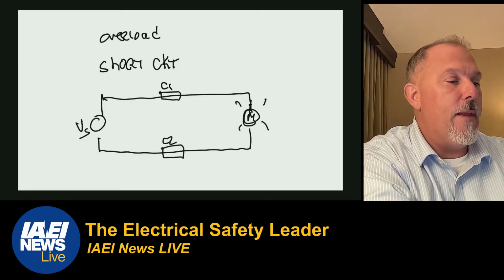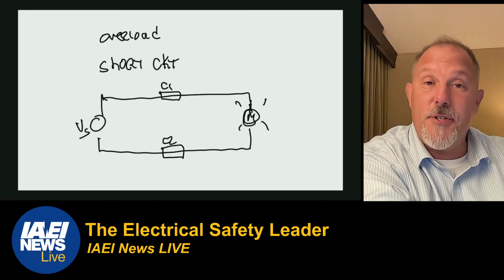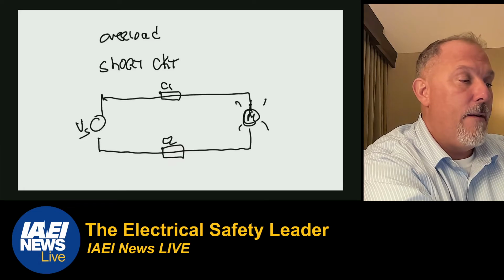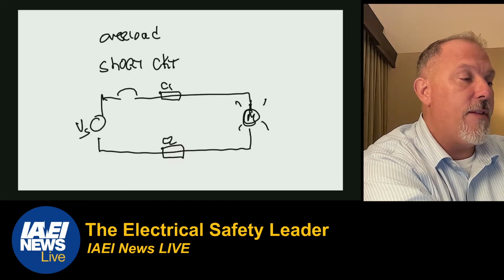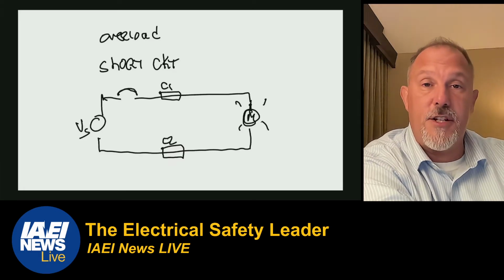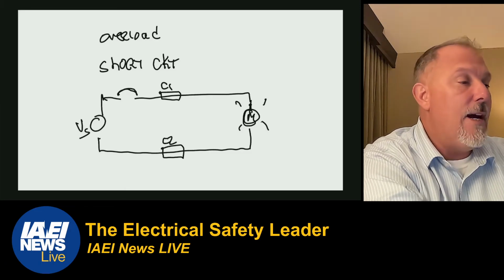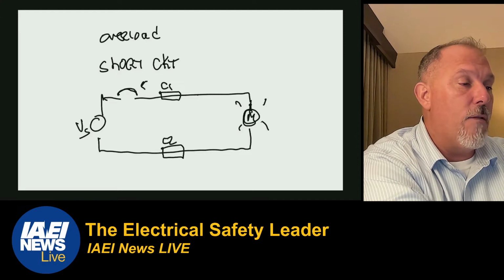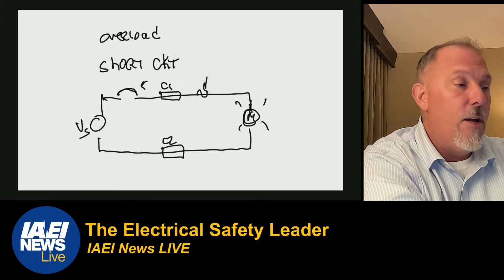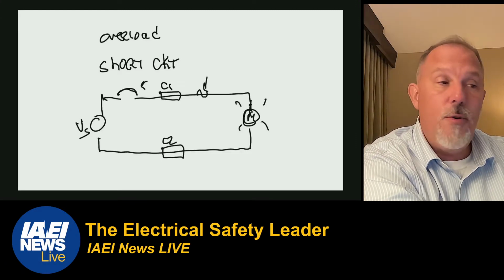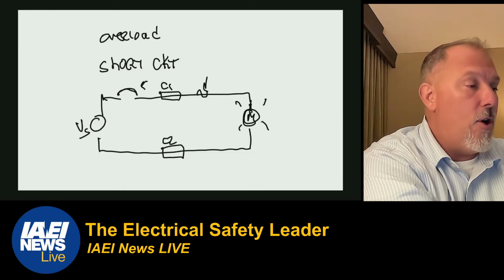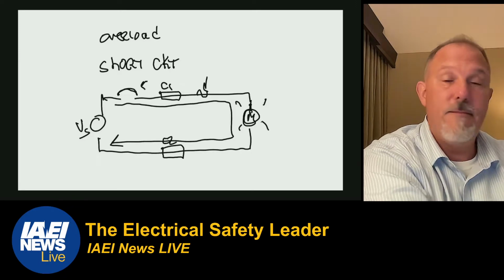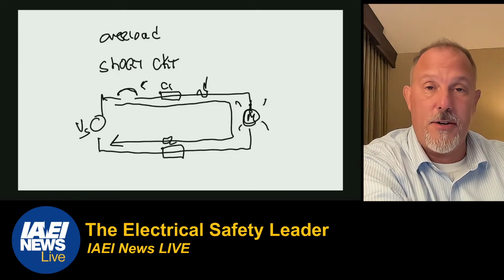So, because we're talking about a motor circuit, if I put an overcurrent device here that's providing short circuit protection for this circuit, I could put my overload protection here. I could put my overload protection down here. With regard to overloads, they stay in the circuit. An overload will stay in the circuit.